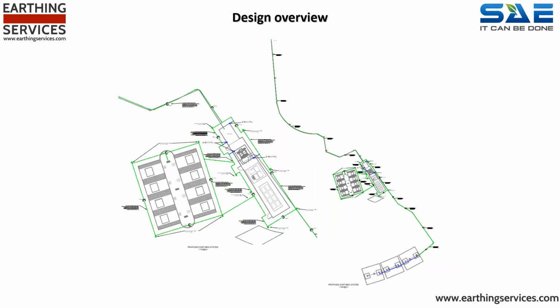The horizontal electrodes were 120mm square hard-drawn bare cables encapsulated within concrete and reinstated with native soil. This conductor needed to be installed at a depth of 1200mm to ensure it was placed within the lower resistivity layer that we would only have known was there due to the soil resistivity survey undertaken.